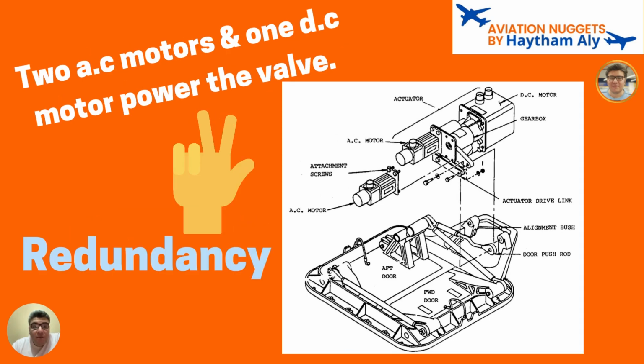Regarding the power, on the outflow valve doors we have a mechanical linkage. This mechanical linkage is operated by an actuator, and this actuator may be powered by three motors. We have three electric motors to operate the outflow valve. As you can see here, two AC motors and one DC motor power the valve.